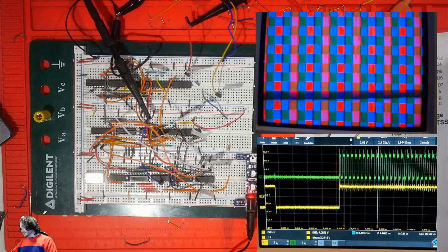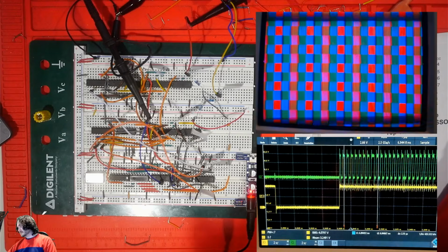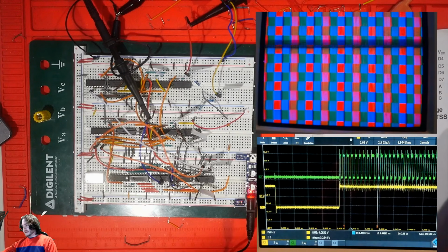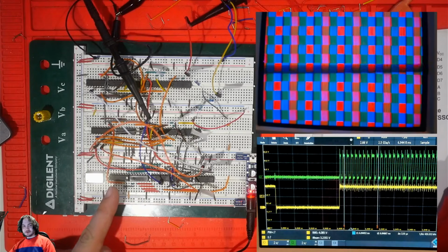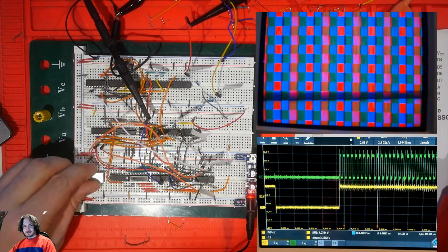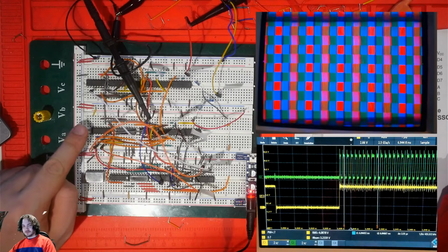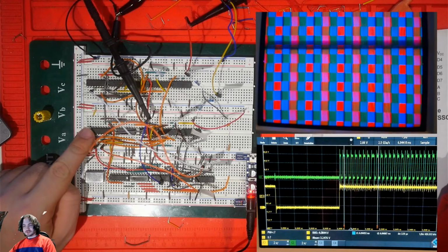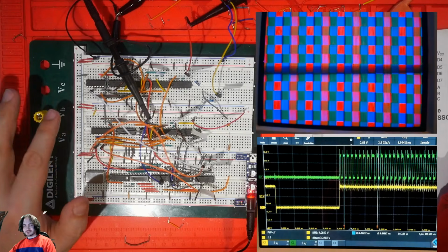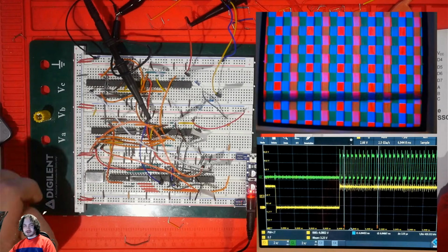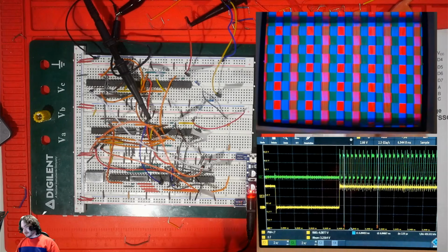As a bonus, we already have a 4040 counter on here to count cycles of the 28 megahertz chip. We have a counter that produces counts towards the H sync, and then one that makes V sync. We could use another counter.